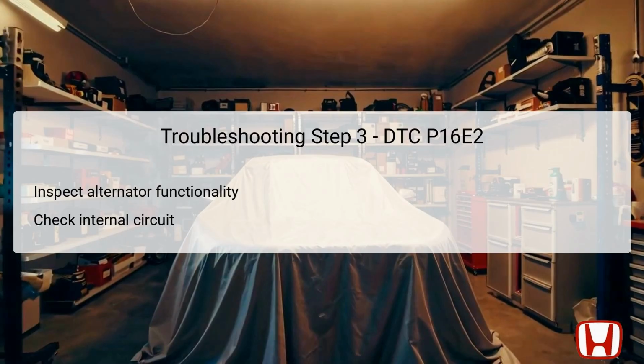To perform this inspection, disconnect the alternator and conduct a test to verify its operation under load. Ensure that the alternator does not exhibit any signs of shorting or other operational failures. If abnormalities are detected during this section of the inspection, further diagnosis or replacement of the alternator may be warranted. This thorough assessment is vital to ascertain that the alternator is indeed functioning optimally.